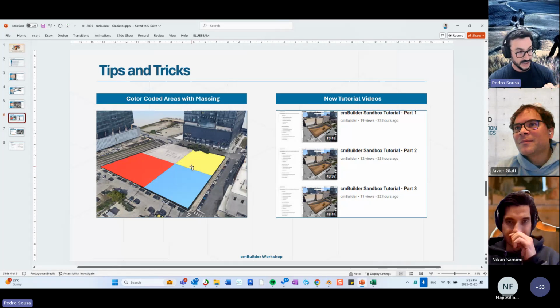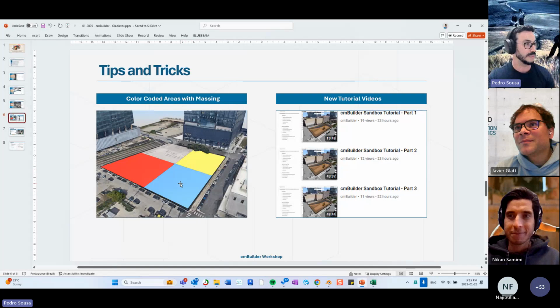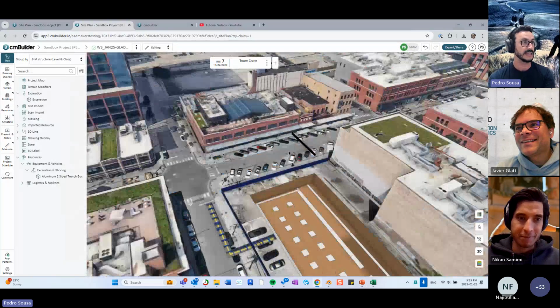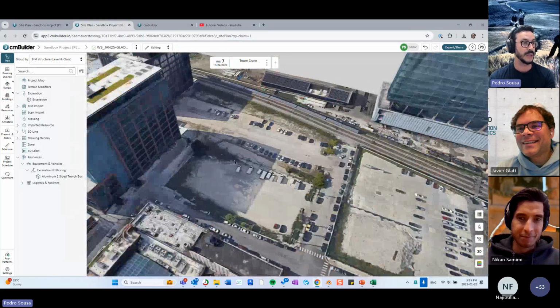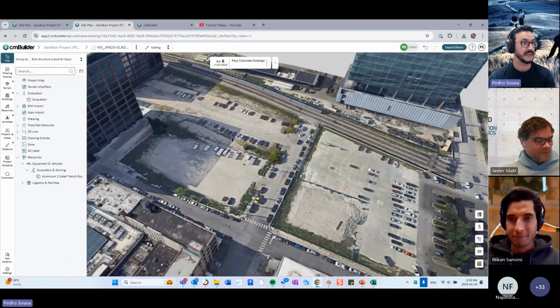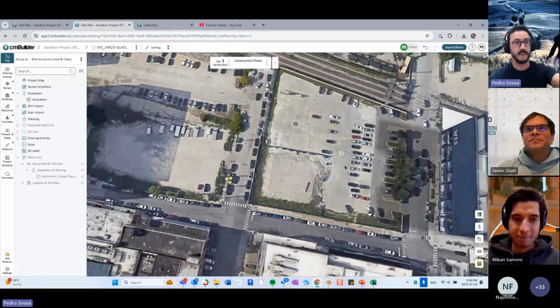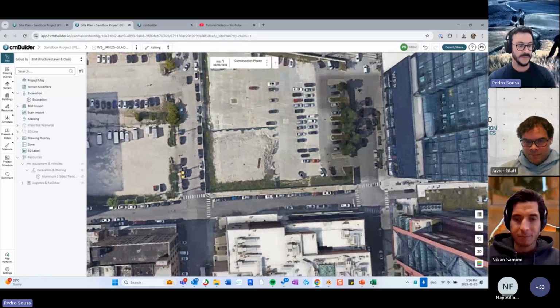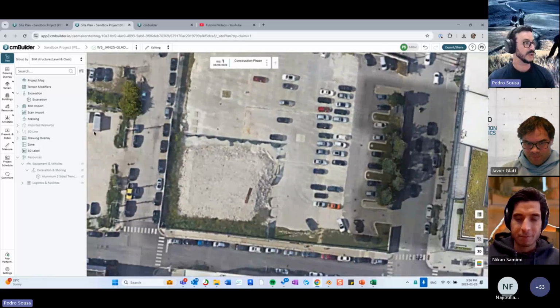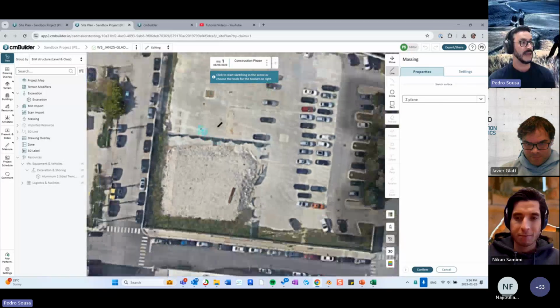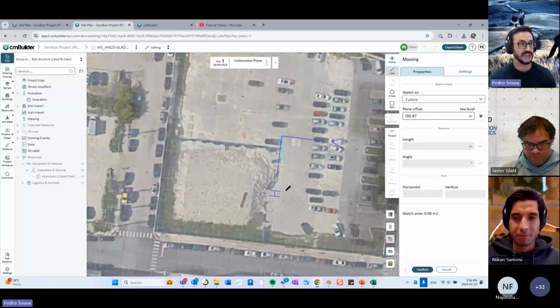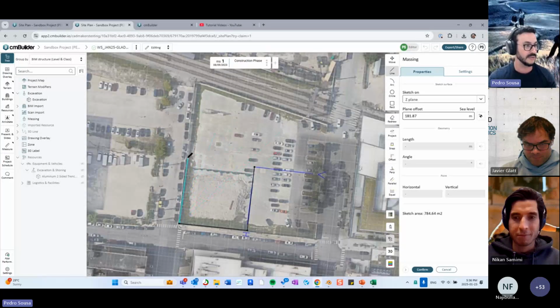If you have a huge area, you're going to be working a lot with these elements. So what I suggested for that user, and I think it really helped, was to create this with massing instead. In a situation where I want different zones related to clearing this area, then pouring concrete and putting formwork over there, what I would do is create a massing, and I will do the first shape of the staging that I want. So if I wanted to divide this area into 4 stages, I will go ahead and do this.